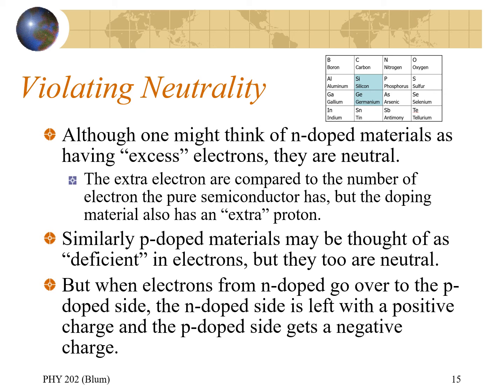So again, aluminum doped silicon would be neutral. It's when we bring the phosphorus doped and the aluminum doped silicon together, and some of the electrons from the phosphorus doped side went over to the aluminum side, it's then that we would get a real charge separation.